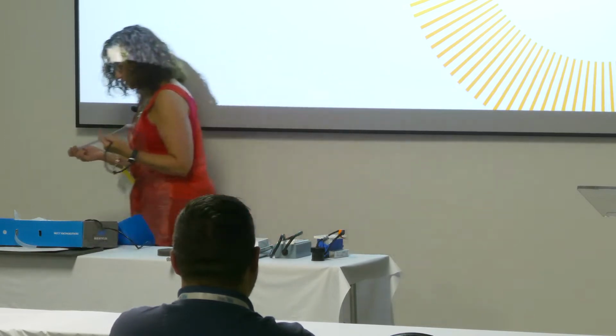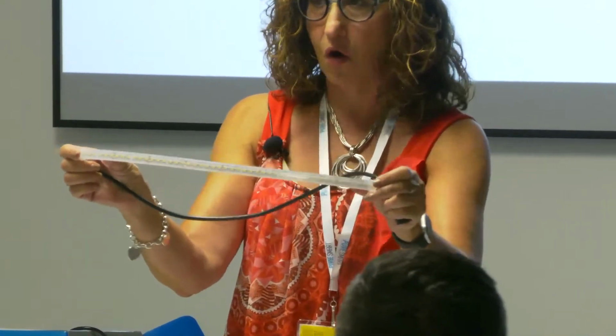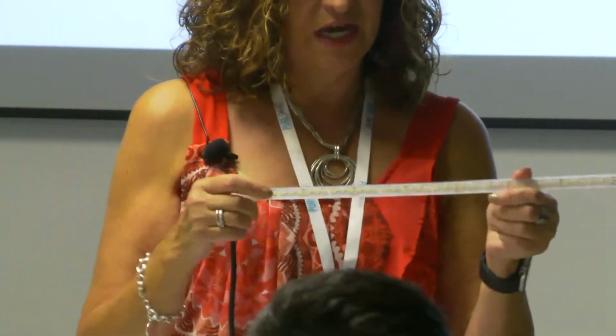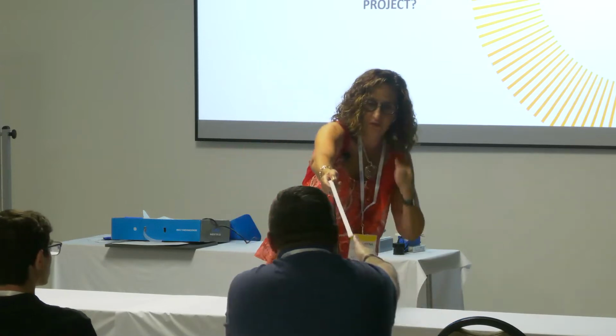I can show this to you guys, and this one, since it's not connected, we can pass around. This is actually a tunable strip, and you can see that there are two different LEDs on the strip. That's how all tunable white fixtures are set up. So when you look at a tunable white catalog number, for example, this one says 1835 on the back. One of these chips is at 1800 degrees Kelvin. The other one is at 3500 degrees Kelvin. And you're going back and forth between the two. You guys can pass that around if you like.